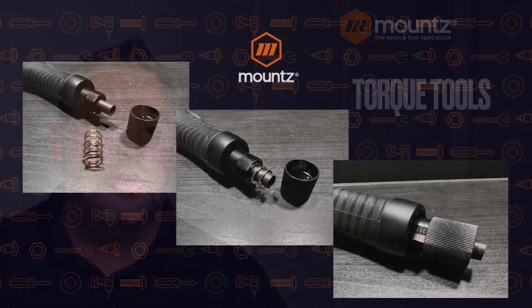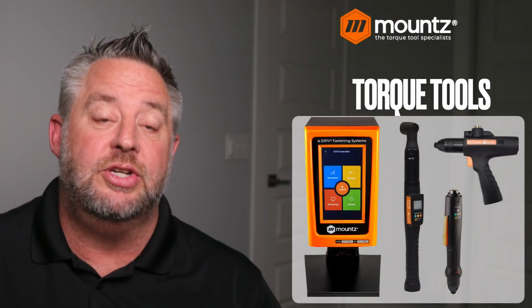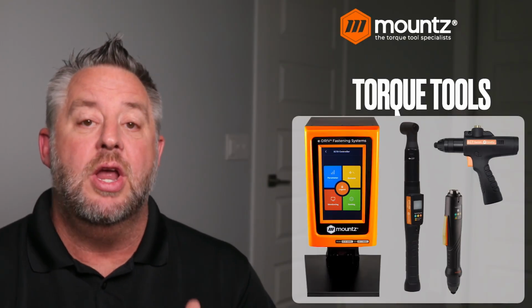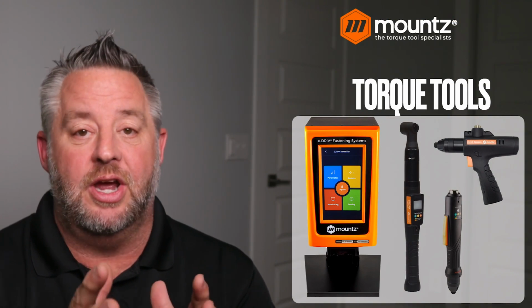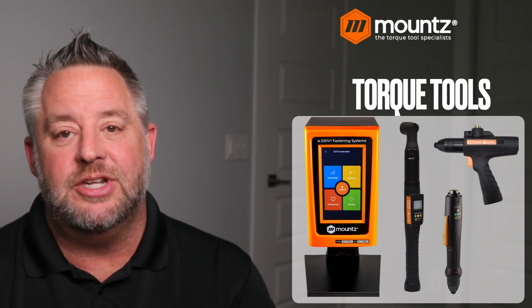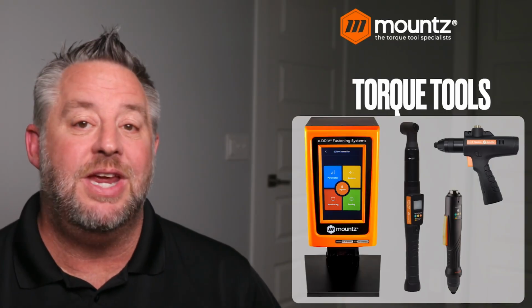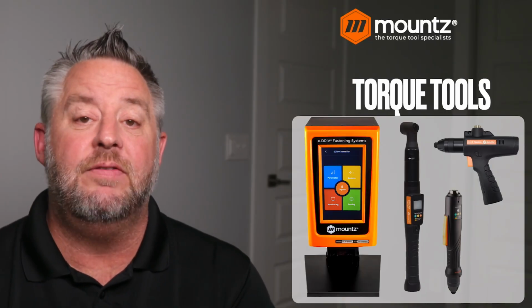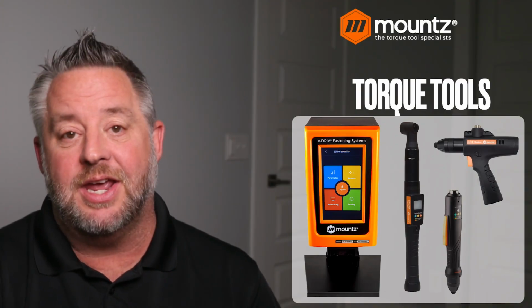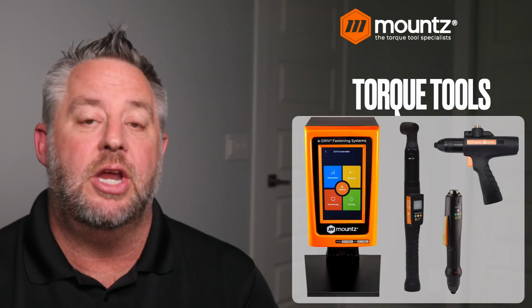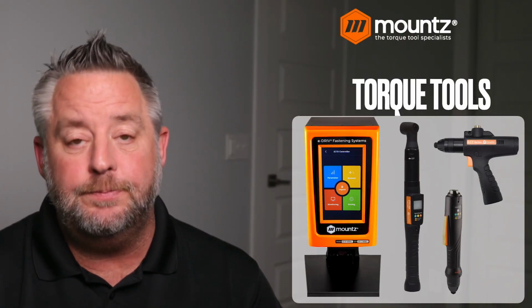Now there's another style of electric tool, which is a DC controlled type of tool. These are basically a computerized tool that gives us the ability to shut the tool off based off of either a sensor that is inside of the tool, or we may take a current draw from the system and equate that to a certain torque value.